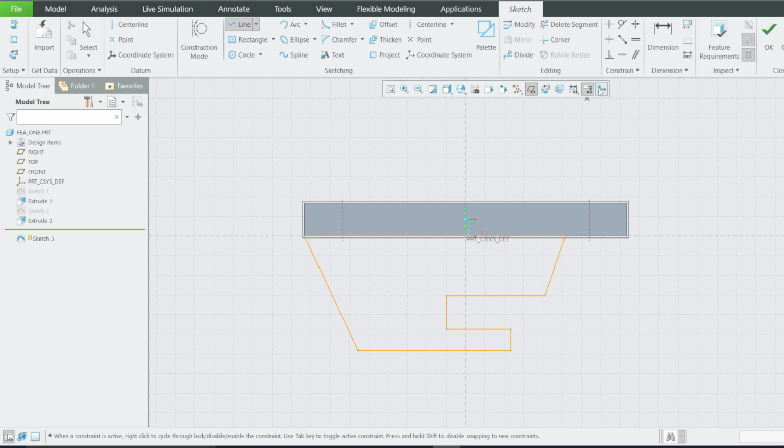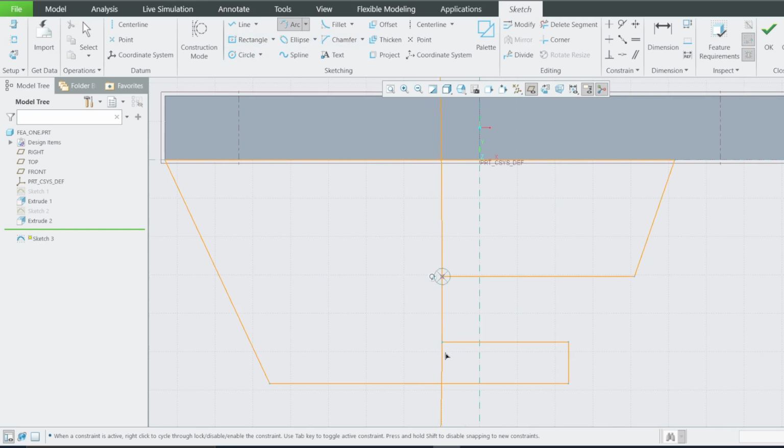loop. Then I want here to have, I can select an arc here, 3-point arc. This point, instead of a 3-point arc, let me select center edge. These are center edge. Just select one. You see, when you select an arc that is a center edge, you have to start by selecting the center, then edge. If you go like this, the circle is like this. If you go the other side, it becomes counterclockwise, as you can see, like that. Then this one I can delete.